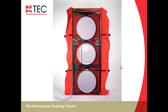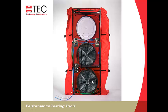The next step is for pressurization testing. We'll need to spin the fans around. So we'll turn the first fan around, second fan, third fan. Now our rings are on the outside. And typically we won't use rings for a big building test. If our fan pressure gets low, we'll just turn one fan off rather than putting rings on.